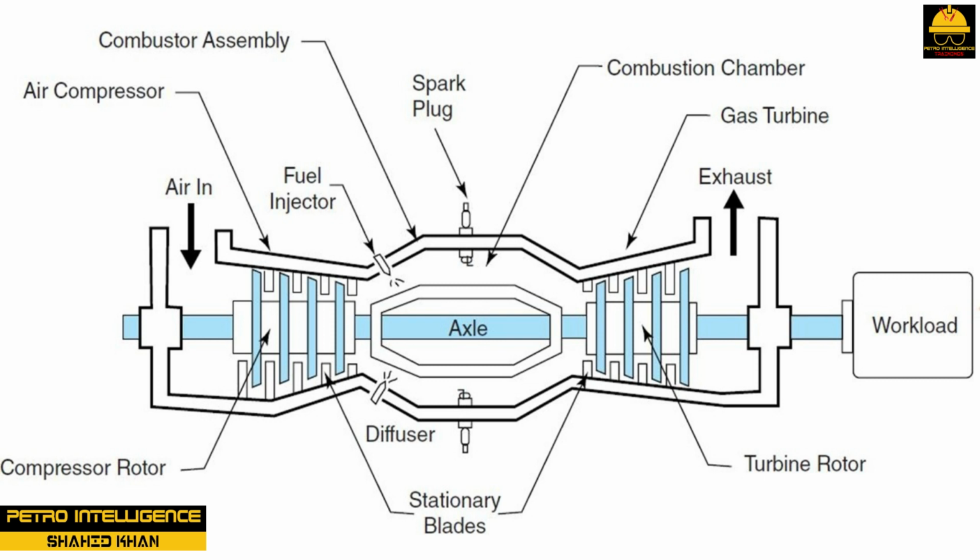Each of these areas has a number of critical components, and they all are linked by a common axle. The compressor consists of the compressor rotor assembly, stator blades, rotor blades, compressor case assembly, air inlet filter assembly, bearings and seals, and compressor diffuser assembly. The combustion chamber consists of a fuel injector, combustor housing assembly, gas fuel manifold, bleed air valve, and igniter.